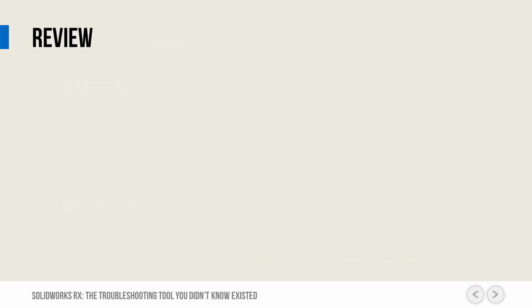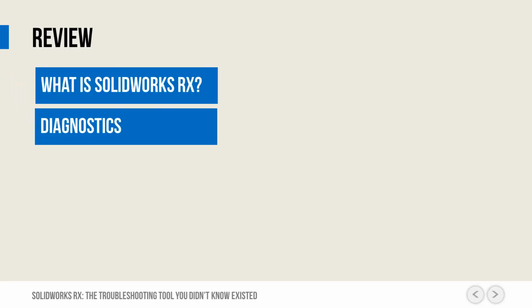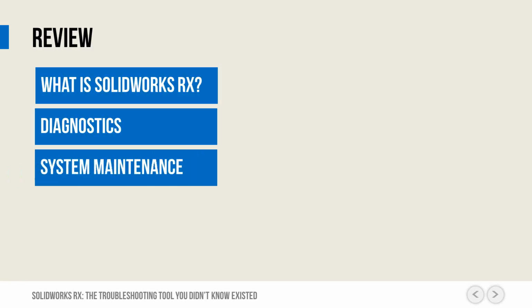So let's go ahead and review real quick the topics that we've discussed. What is SOLIDWORKS Rx? We went through that. It's a utility to help you troubleshoot and diagnose issues with your computer and your SOLIDWORKS installation. We went through the diagnostics tab of the SOLIDWORKS Rx interface that basically gave you a listing of all of your hardware specs, RAM usage, and folder mappings within SOLIDWORKS, and indicated if there were any immediate issues with any of those items. We also reviewed the system maintenance, where you could delete temporary files from SOLIDWORKS, from Windows, as well as perform maintenance on your hard drive.